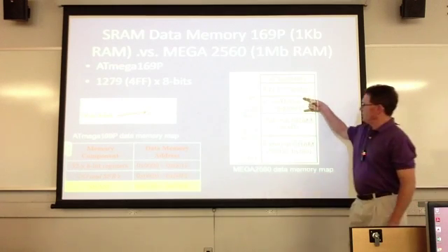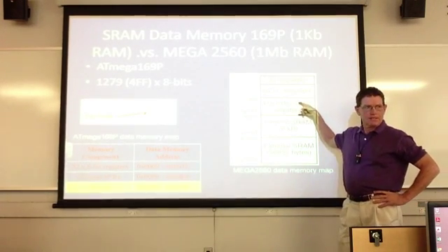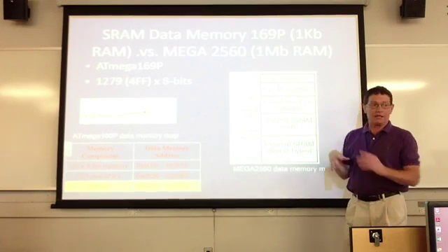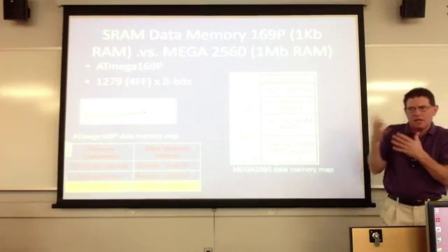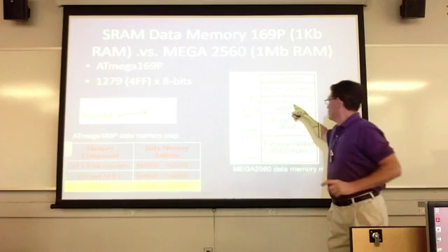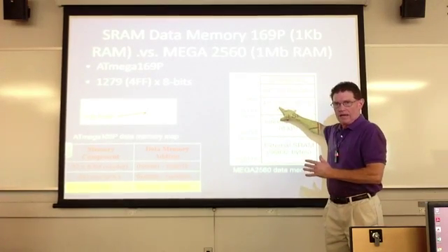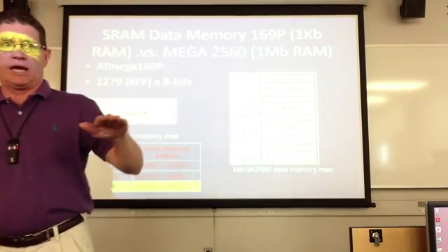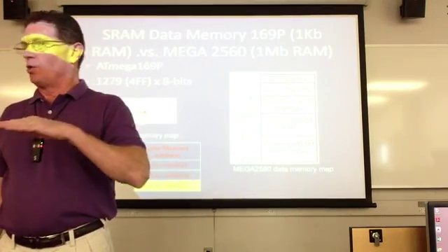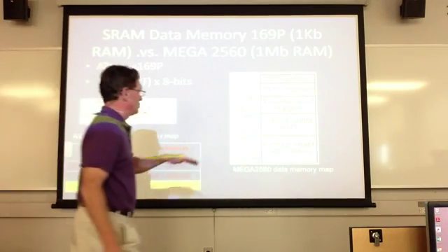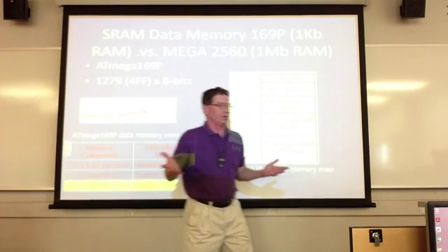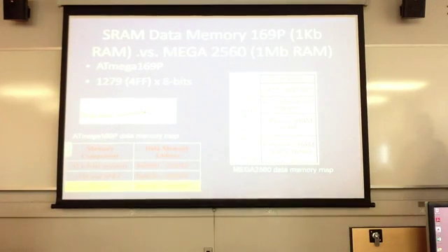We are now writing into here. All right, that's where we're writing to. So you've got to be real careful when you write into here, because if you notice, it didn't write an A3, it wrote an A2. In some of these registers, and these are all 8-bit registers, some of the bits are preset. You physically can't write to it. So we were trying to write into a memory location in here that we can't. You basically can't write to it. Okay, so you just have to be careful about that.